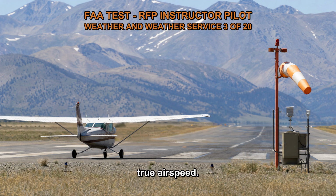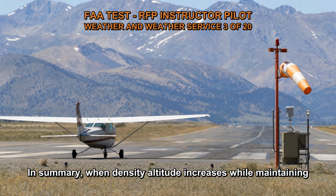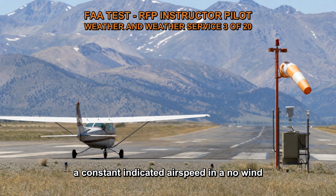Since there is no wind to affect the aircraft's motion relative to the ground, the ground speed will be the same as the increased true airspeed. In summary, when density altitude increases while maintaining a constant indicated airspeed in a no-wind condition, the true airspeed will increase. As a result, the ground speed will also increase since there is no wind to affect the aircraft's motion relative to the ground.